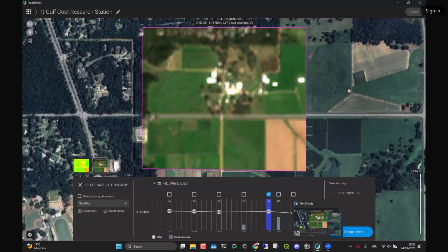Yes? When you get the pictures with your drone, warp or de-warp? Very much de-warp. Go with the warped setting. Don't check that box, please. If you do, we're going to be doing double corrections, and you're going to see some really weird stuff happening.